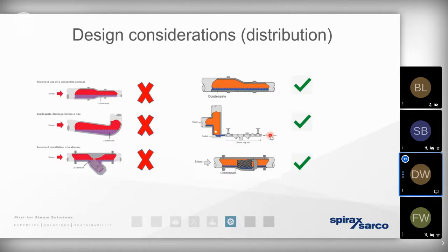And whenever we're locating a Y-type strainer in the distribution pipework, we want to ensure that the downward pointing leg, that would otherwise become a point for condensate to become trapped, has been rotated so its leg is at 90 degrees. And as you can see here, the condensate can then pass freely and easily across the strainer to a point where it can be drained away. If we didn't observe this good working practice, condensate would become trapped in the distribution network. And it's at that point that we're exposing ourselves to that erosion, corrosion, water hammer. Steam's going to become degraded and have less energy in it.